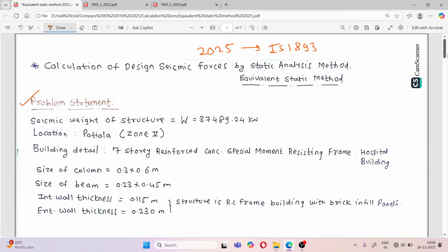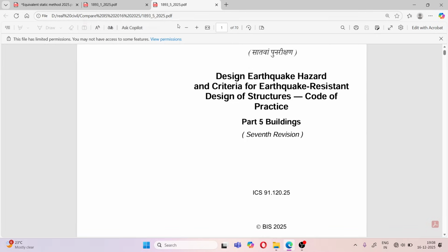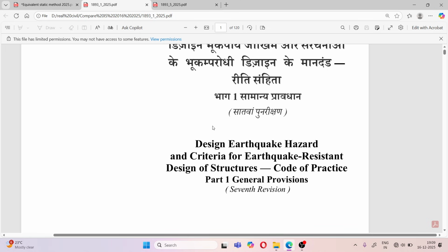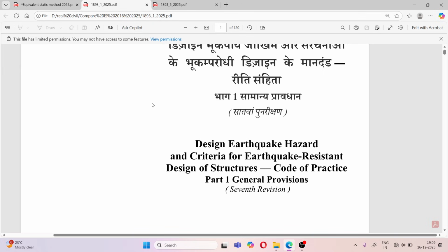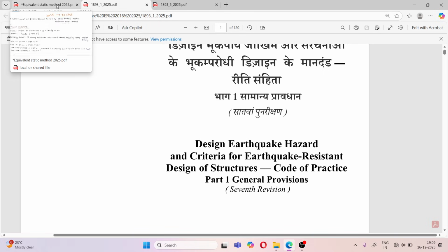Okay, so let's start. If you don't know how to download the IS code, I have made a video. You can see the link in the description box, or you can click on the I button. We need two codes basically: Design earthquake hazard and criteria for earthquake resistant design of structure, code of practice, Part 1, and Design earthquake hazard and criteria for earthquake resistant design of structure, code of practice, Part 5, Building. The first one is general provisions and Part 5 is related to buildings, and we require both codes.